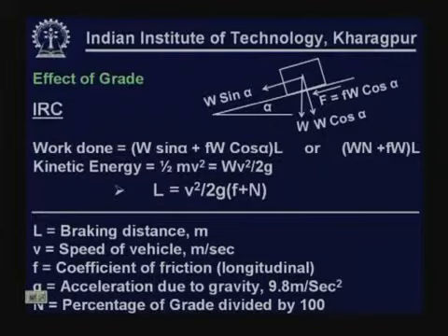So, therefore, the frictional force is coefficient of friction multiplied by the component of weight in the perpendicular direction. So, force equals coefficient of friction into weight into cos alpha.